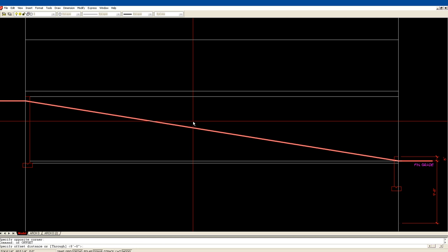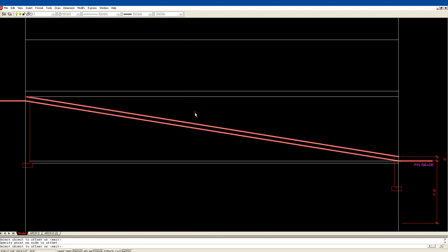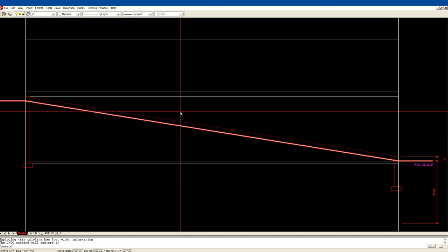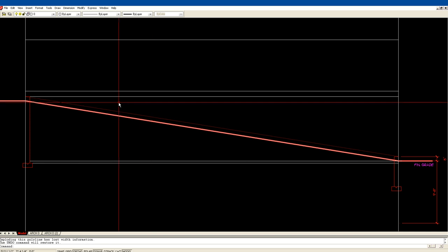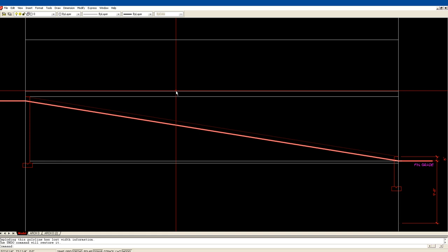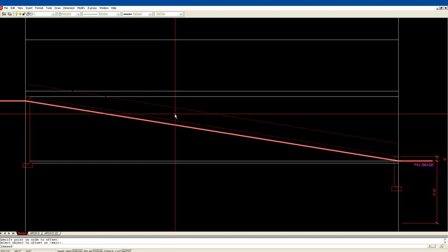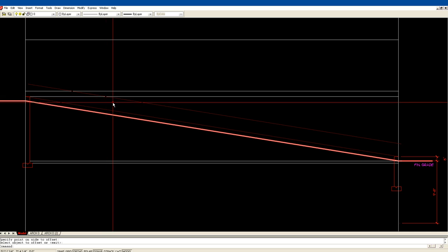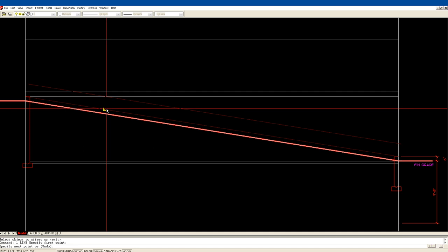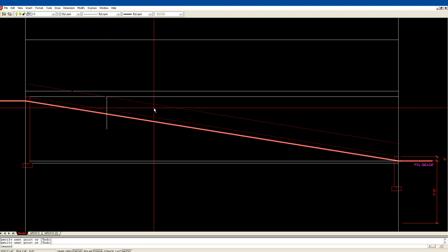We're just going to offset 8 inches. There's our minimum 8 inches along this wall, right? We have to have concrete above that line. I'm just going to explode it. Now, there's a whole bunch of ways of doing this. We can offset 24. So right there is where I'm going to make my first jog, and I'll just run it along there.